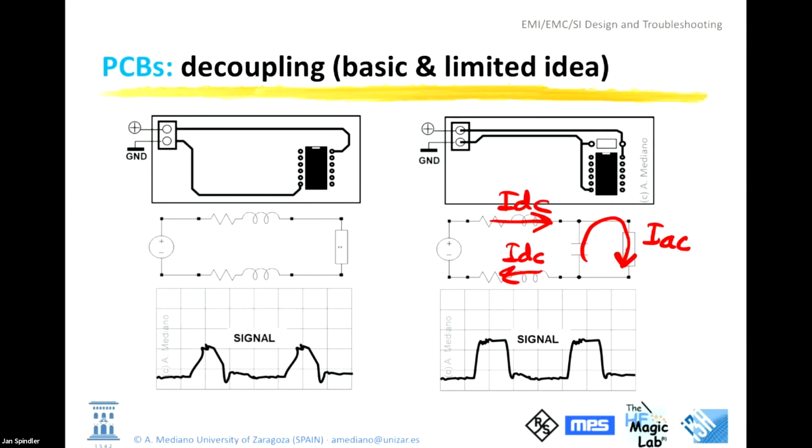So depending on the component you are decoupling, it's not the same: audio, power electronics, digital electronics. You will need a big capacitor for big transients, but additionally you will need a broad frequency response if you have energy at very high frequencies, hundreds of megahertz. So you need to identify how many capacitors, what technologies, where you put the capacitors, and what about the parasitics in the layout, no? The idea is that doing this, the loop that was dangerous previously is now a very small loop if you do things in a good way.